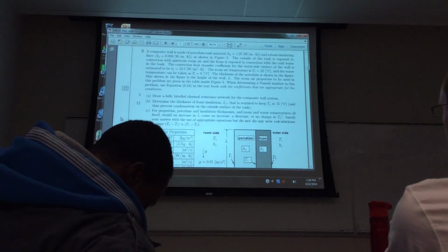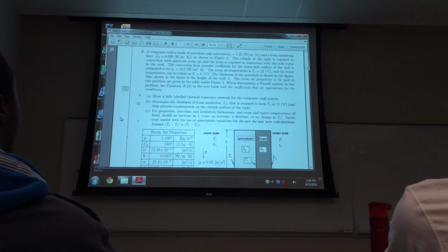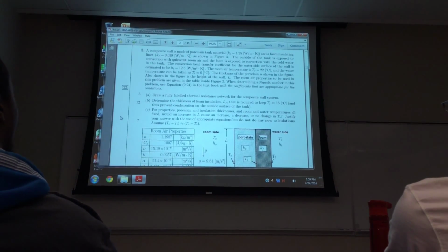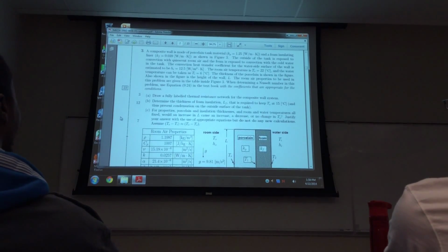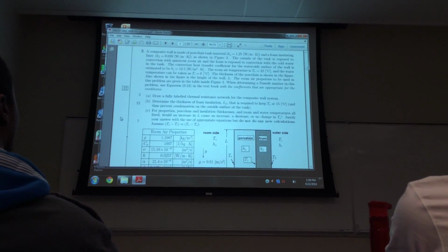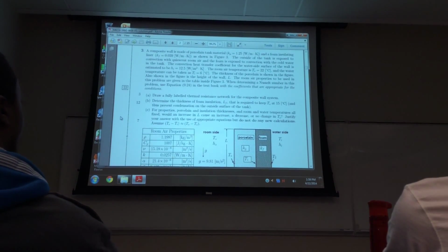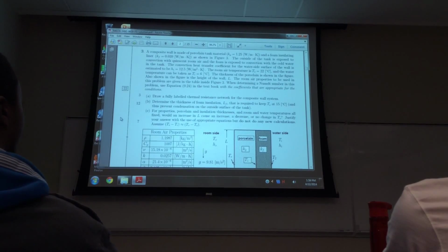So you immediately say, somehow here I've got to be able to use a Rayleigh number and some kind of free convection equation. Steady state, 1D. And so then it depends on the T minus the T infinity. That's your driving force. Whether it's heating or cooling, Rayleigh number is always positive. Use the correct delta T, the positive sign.